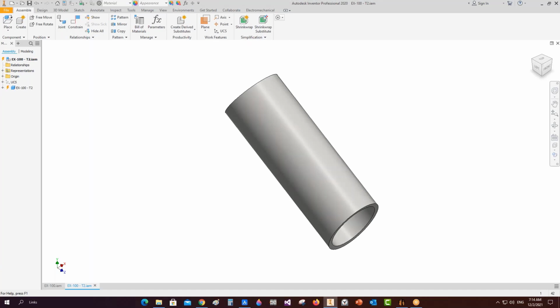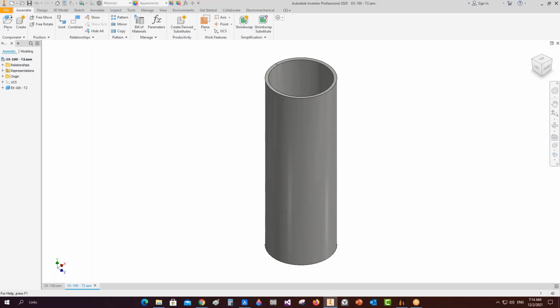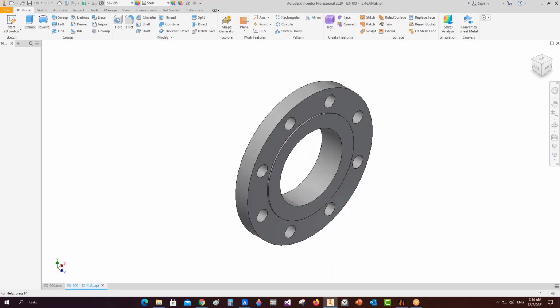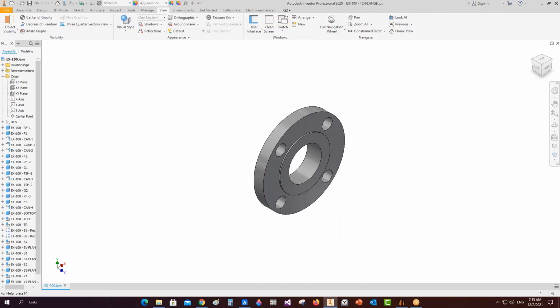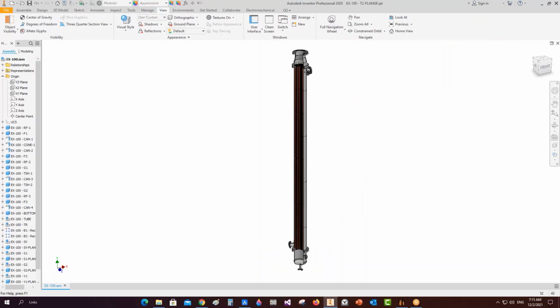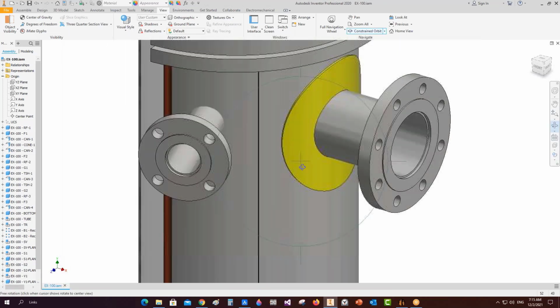Right? So here, after completing the equipment assembly, we will add a tailing lug and a lifting lug. After that, we will add the support clips, which is the support lug. After that, we will proceed with drawings. Here we add all nozzles. We have those nozzles here.